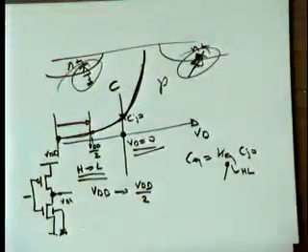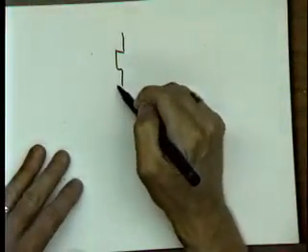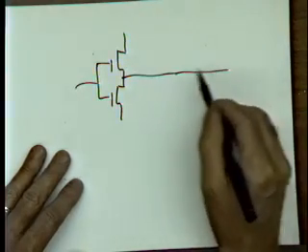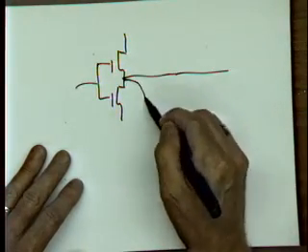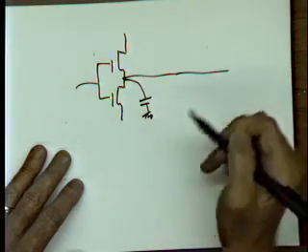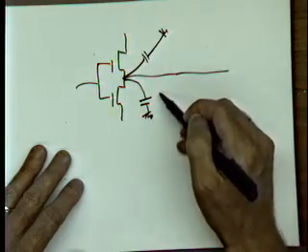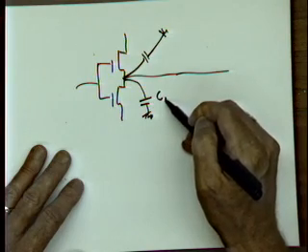Yes. When calculating C load, so you lump together all the capacitance. That's right. But there is one from the V out to the VDD, right? There's a bunch of them, right? But it doesn't matter. So you lump all your capacitance. So what do I get here? Well, I have my drain to bulk from the PMOS. That's that capacitance you just drew on the top.